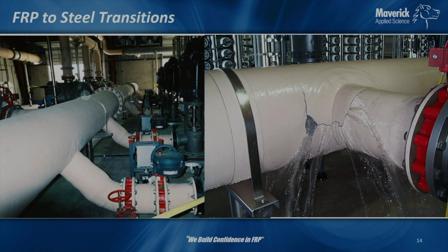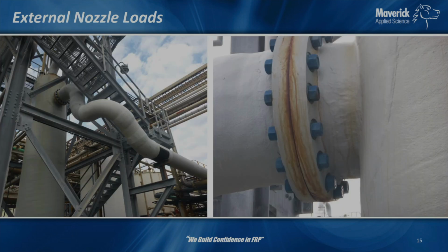Carbon steel, every material expands, and it was moving about 3/4 of an inch is what we found. So when we're analyzing that system, that's an input we have to put in for that interface. We just can't call that rigid and say it's not going to move, because that whole vessel is moving. So this was a project that we were brought in on after the fact.